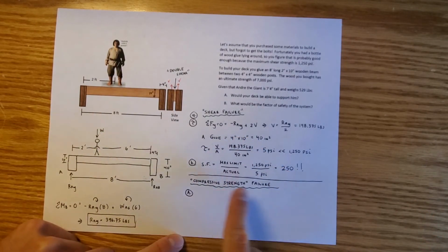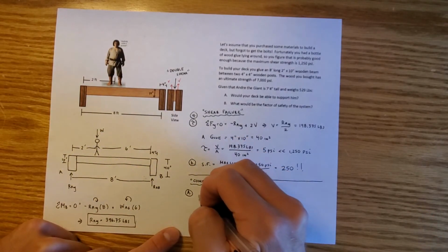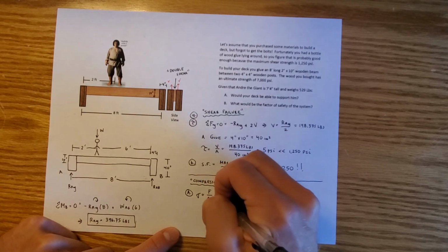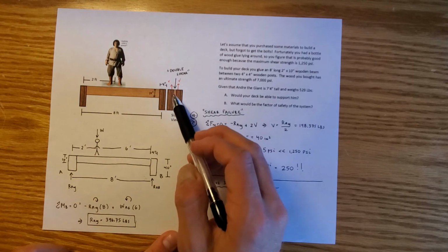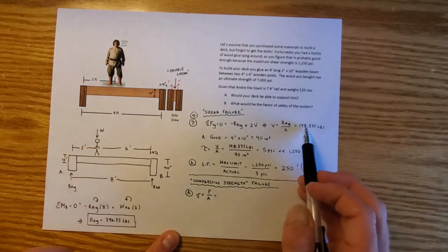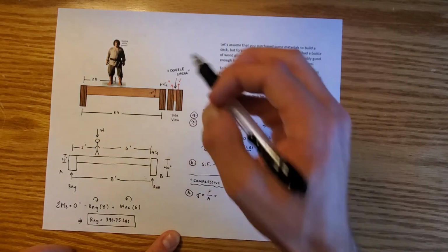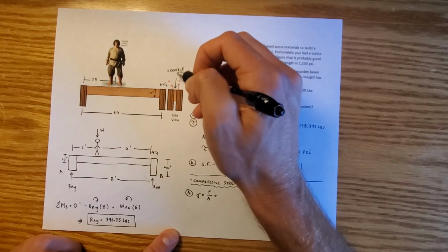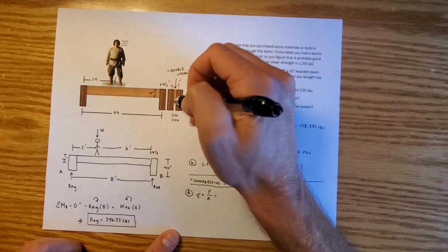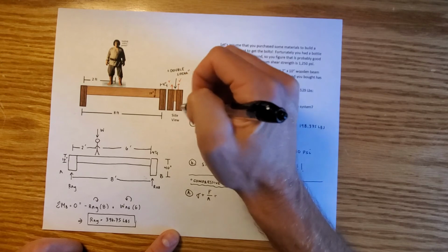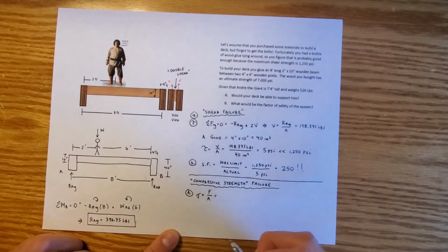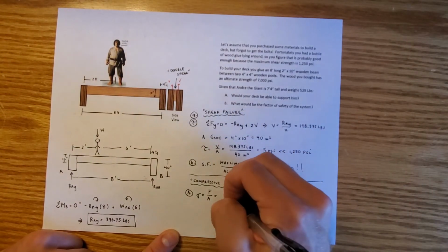So now we're going to check compressive strength failure, and we're going to check the normal stress. We know that normal stress is going to be equal to the force over the area, which in our particular case, each of these beams is experiencing 1/2 of RAY. So it's experiencing 198.375 pounds. The reason being that when this is pushed down here, the RAY, the shear force is the shear force along both of these sides. Well, that shear force is going to be more or less the same force that's compressing this piece of wood.